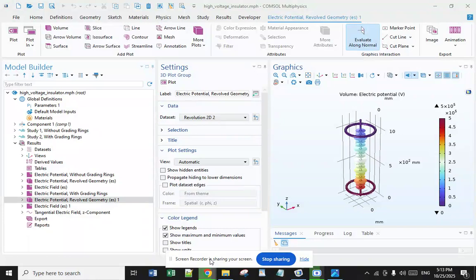The next is mechanical strength. High voltage insulators must also have high mechanical strength to withstand electrical conductor loading and extreme weather conditions. The next one is resistance to contamination. High voltage insulators are exposed to extreme environmental conditions, including contamination by dust, snow, ice, and rain. Insulators must have a high resistance to contamination to maintain their dielectric efficiency.